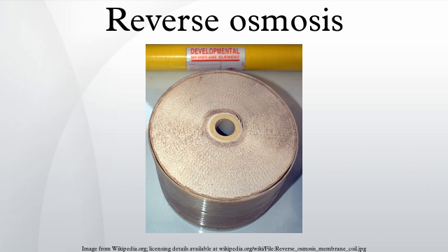Up to 50% of the seawater input can be recovered as fresh water, though lower recoveries may reduce membrane fouling and energy consumption. Brackish water reverse osmosis refers to desalination of water with a lower salt content than seawater, usually from river estuaries or saline wells. The process is substantially the same as seawater reverse osmosis, but requires lower pressures and therefore less energy. Up to 80% of the feed water input can be recovered as fresh water, depending on feed salinity.